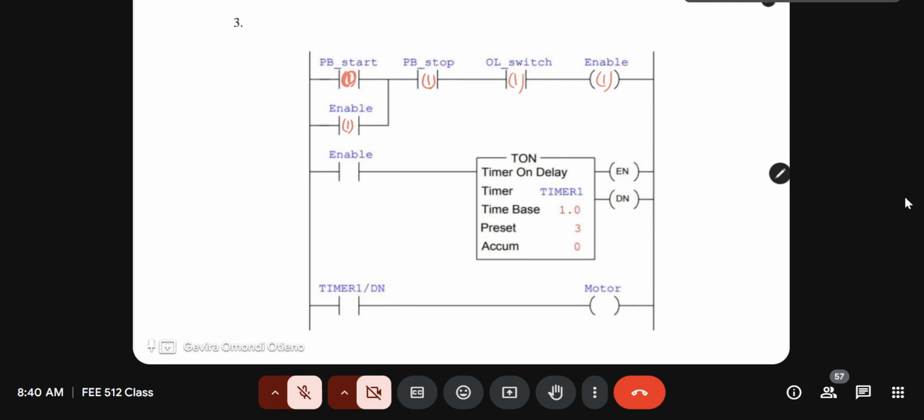That one, the latching, we already know that. I just want to figure out what happens to this ladder diagram. So rung 1, rung 2, rung 3. In rung 1, let's have the enable output being given a logic 1, and therefore that is transferred as an input of rung 2. So rung 2 has gotten a logic 1 because it's the input.